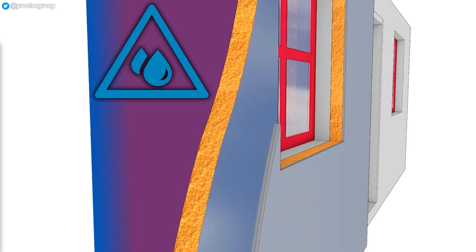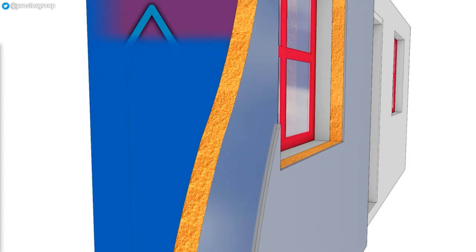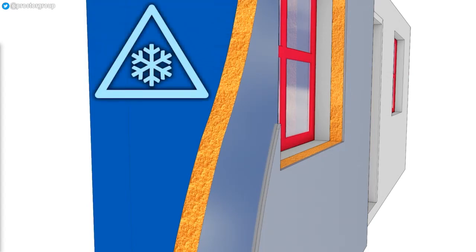Secondly, some insulation types such as rigid foams can prevent the drying out of condensed moisture inwards into the building, further compounding the problems. If not properly accounted for in the design, this moisture accumulation can continue unchecked, leading to increasing problems with damp and mould over time, and in extreme cases, causing the masonry to degrade due to freeze-thaw cycling.